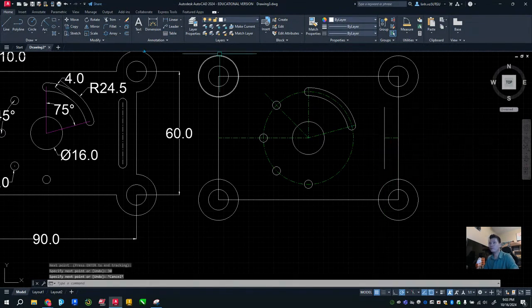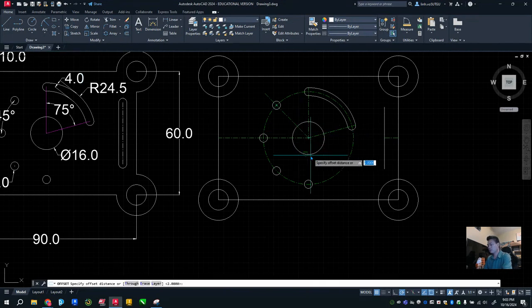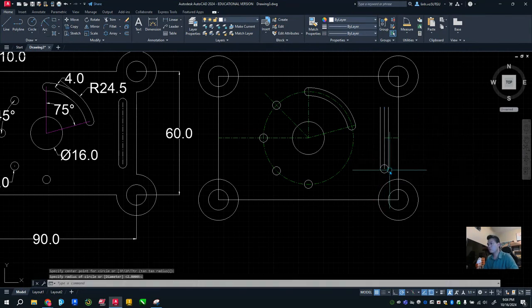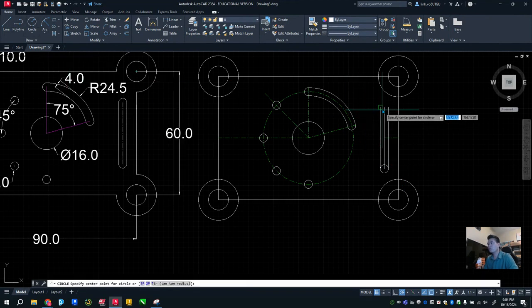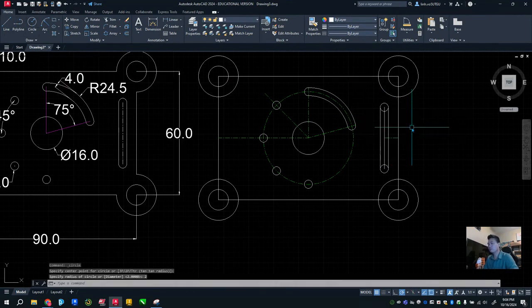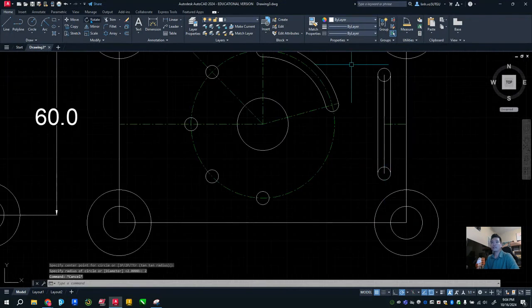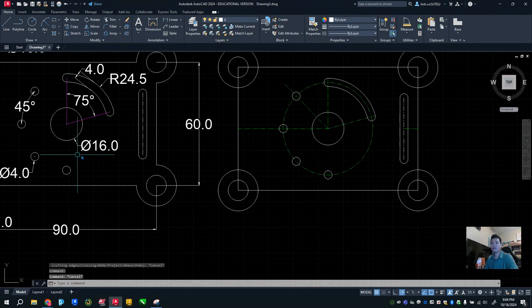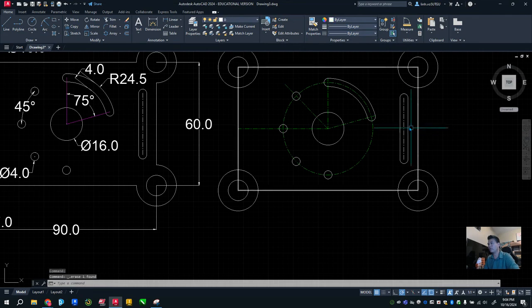Okay, hit escape. Now I'm going to go ahead and offset this 2 units to the left and 2 units to the right. Okay, go to circle to do that. Also go to circle. It's just 2 in radius, and I can go ahead and trim out the part that we don't need. And this right here, they want to be a center line like so to show up on the drawing. So I'm going to do that, and then for this one I can get rid of it.